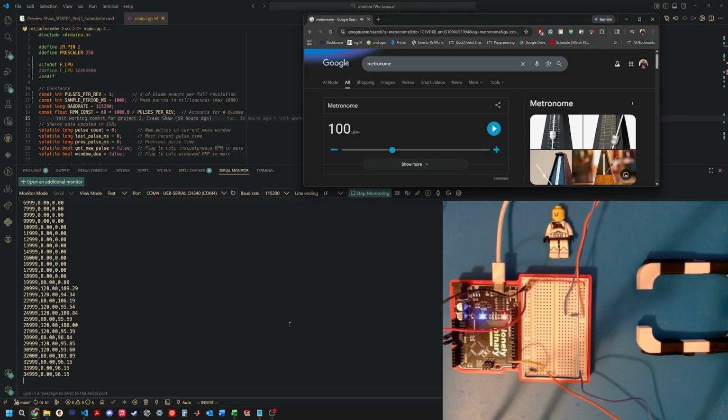So from that output, you can see the CM Palmer method kind of jumps around between 60 and 120. So if you drop a pulse in your 1 second, right, you're going to get kind of wildly different measurements, whereas that 2 pulse method seems to give a pretty consistent timing or RPM measurement.